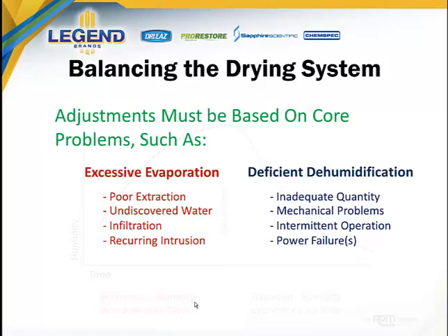If this is the reason or the cause, then consider bringing in temporary power distribution and running clean power through a licensed or appropriately qualified electrician to run the dehumidifier off of a power source that we know we can rely upon. Now, these 8 items, all separate and very unique, most commonly are not considered by restoration contractors when they see a high humidity spike.